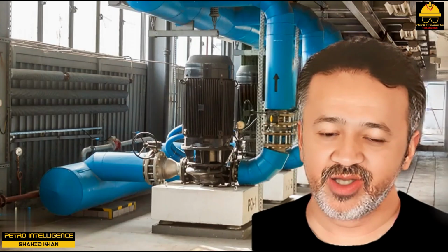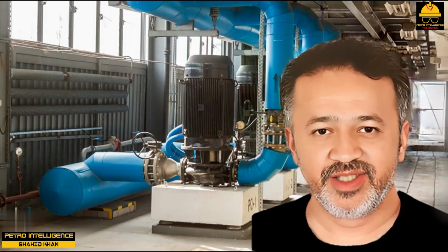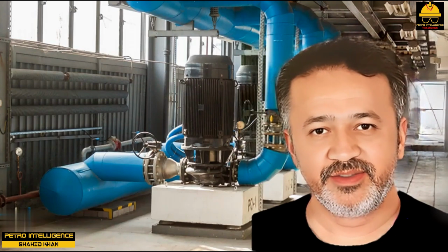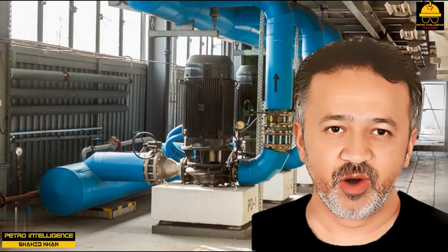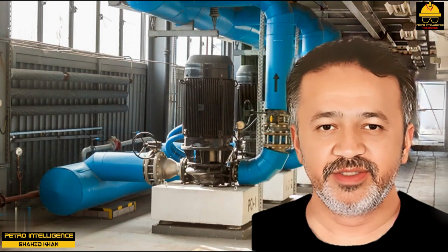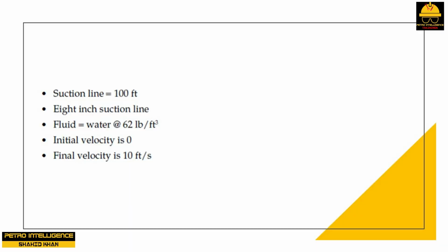Starting NPSH requirement. The need to accelerate the fluid in the suction of a pump is called the starting net positive suction head (NPSH) requirement. To calculate this starting NPSH requirement, let's assume the suction line equals 100 feet, 8-inch suction line. Fluid equals water at 62 pounds per cubic foot. Initial velocity is 0. Final velocity is 10 feet per second.